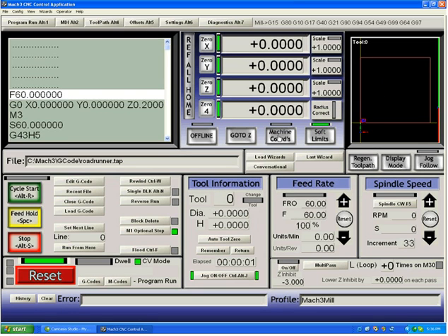When I switch to machine coordinates, you can see that we have a display showing how far away from the home switches we actually are. But if we turn off machine coordinates, we see the result of our G54 offset system has zeroed us. If we regenerate the toolpath, which you must do after playing with referencing and zeroing, you can now see our Roadrunner is going to be cut somewhere in this area of our mill table at a 0 coordinate on our G54 system and at coordinates 32, 37, 16 in our machine coordinate system.